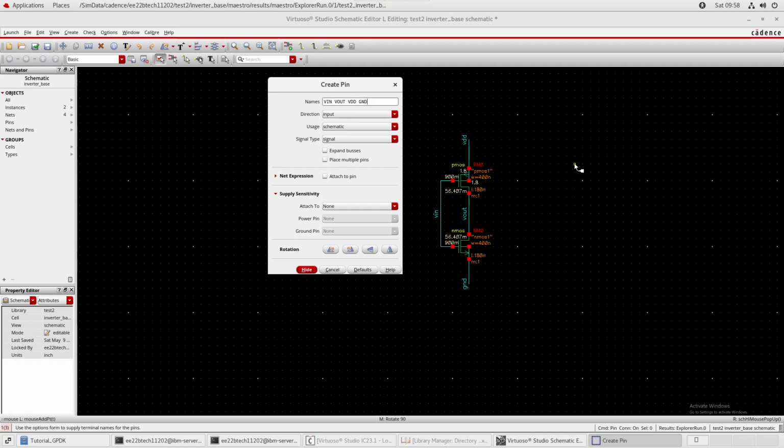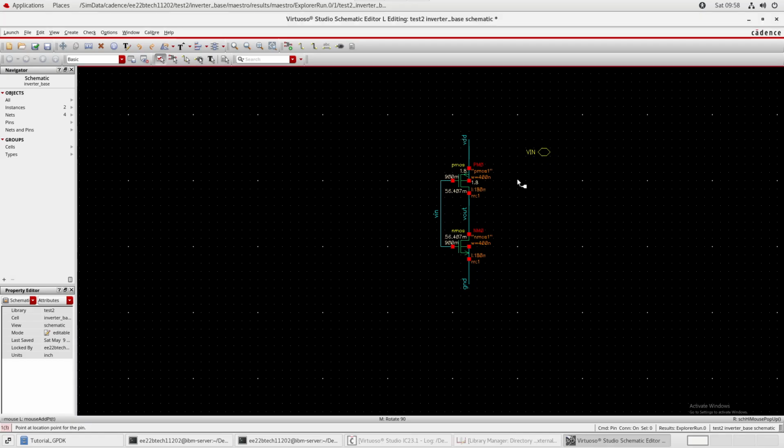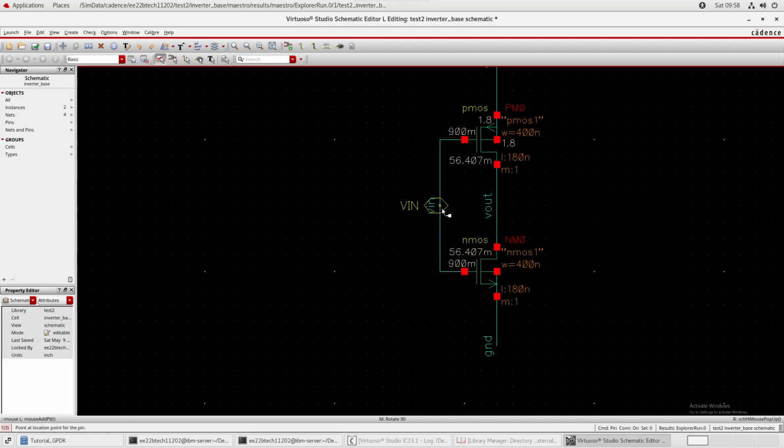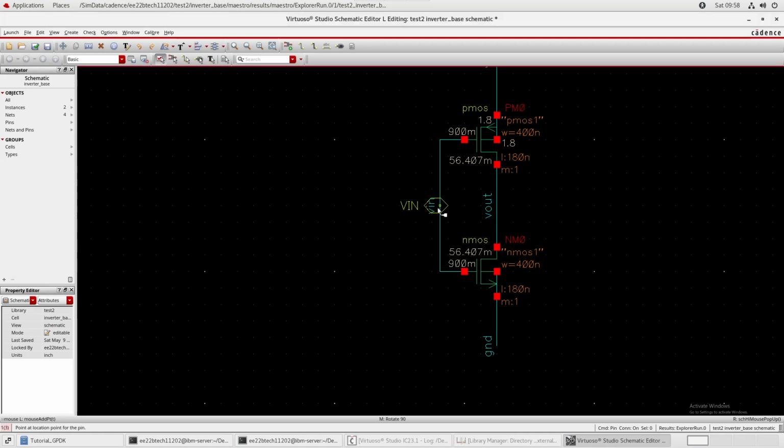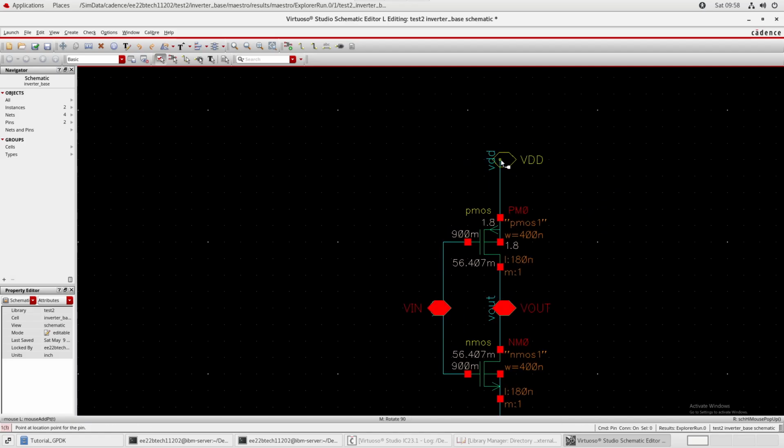The format we usually use is just keep all of them in capital and all the ports as input output. Although some higher amount of value can be achieved by defining the direction and the signal type specifically for each port. So it can help you debug things a bit easier. It can make things a bit easier.